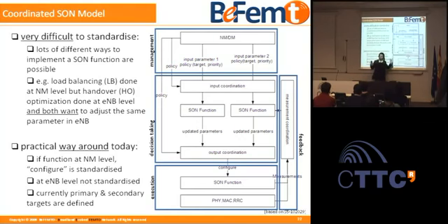Now, how it works in terms of the architectural approach is very simple. You have a management on top, you have the decision taking, you have the execution, and you have the feedback. My network management is defining certain policies. For example, when there's a football match, I want my traffic to be balanced better in this geographical area. This could be a policy. I'm just giving you a high-level policy; there can be more specific policies. They are trickled down to your SON functionalities in the network.